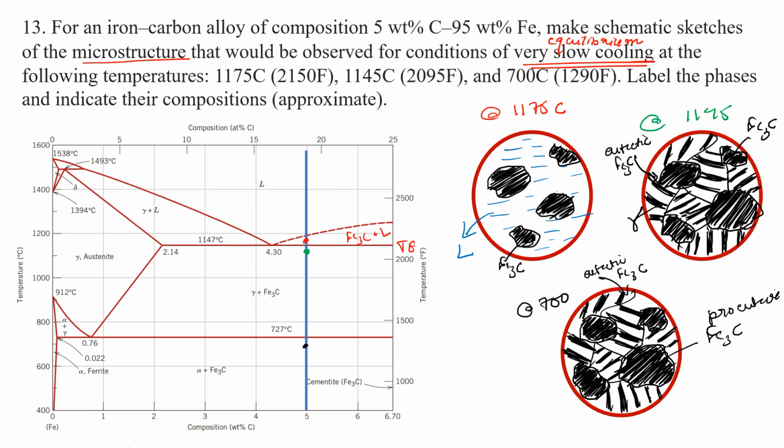And the remaining part is alpha, which is what I show in the red color. So it's very interesting to see that whatever phase was delta has just converted to alpha, very similar to how a pure iron should behave.